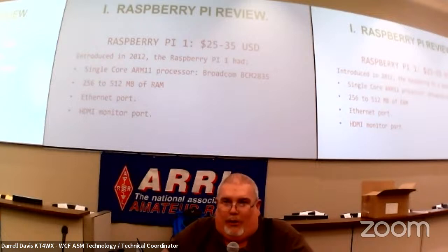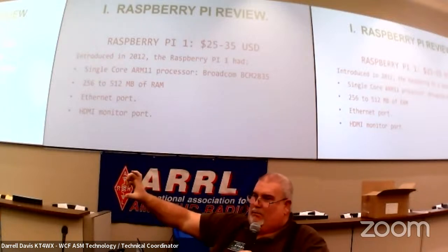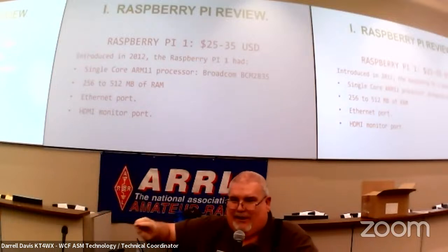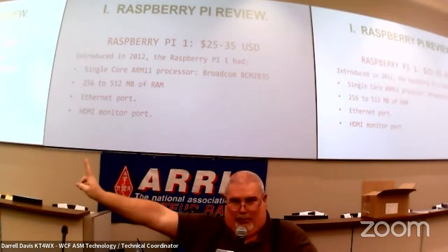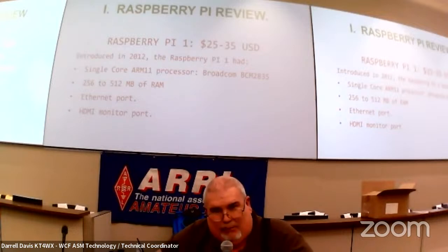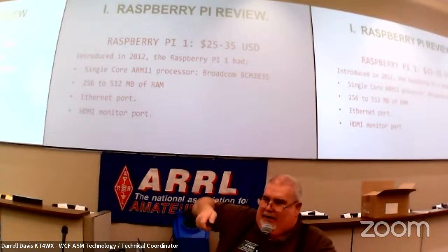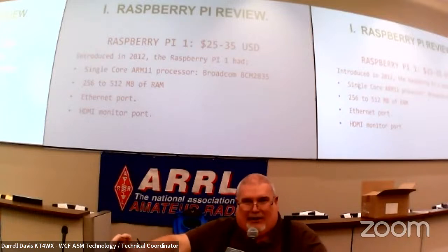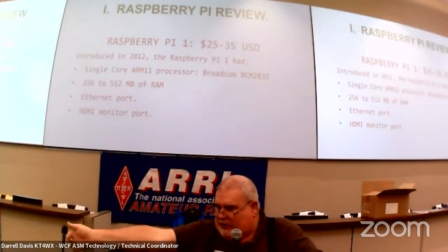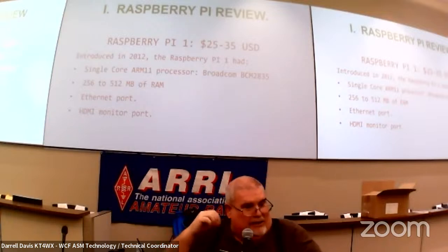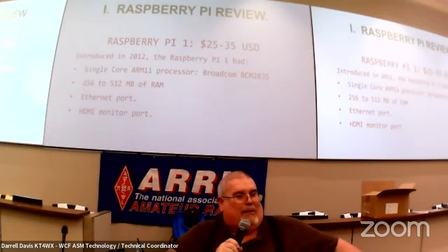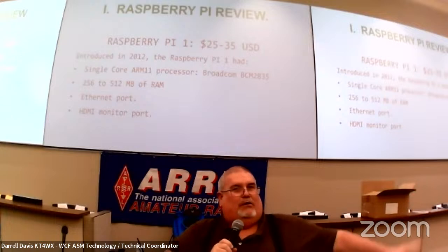But they used an ordinary television. I saw on Facebook a picture recently of this little switch box. We remember what it was, the old one with the slider on it. It had a 300 ohm twin lead output. Now, the televisions actually had 75 ohm F connectors that were cable ready, with the balun on the inside. You had to put a balun on the outside, but it had a 300 ohm twin lead connector. You connected it to your television, one lead went to your computer and one went to the outdoor antenna. So you could switch between the antenna and the computer, with the TV on channel 3 or 2. And now I'm really going down memory lane. Then your computer could display on your television.